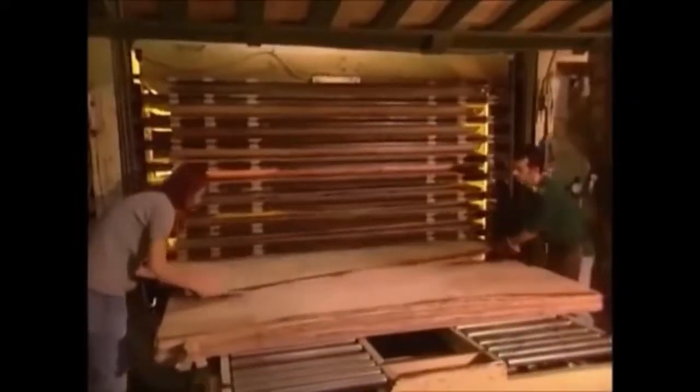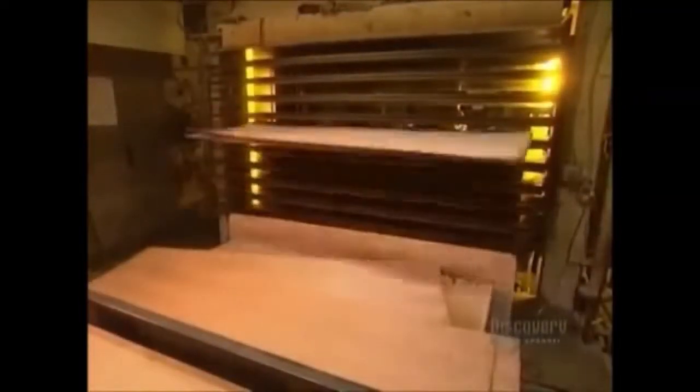They feed the 3 sheets through a hot press at more than 100 degrees Celsius. In a minute and a half, the glue cures, and those 3 sheets of veneer become a 3-ply panel of plywood. Then they sand the panel. Plywood door facings can be made from more than 15 different species of wood, from birch and oak to maple